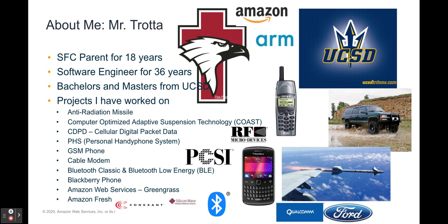The computer-optimized suspension technology was really cool. We were taking the input measurements of the tires on a vehicle, and as we measured that, I would loop that back and apply the right suspension control so that when you're out on a bumpy road, you have a good firm ride, but if you're out on a freeway, you have a nice smooth ride.